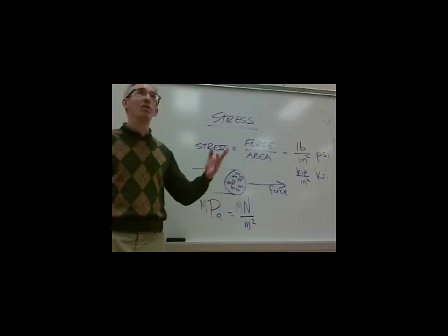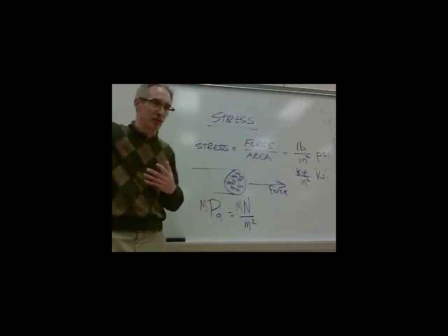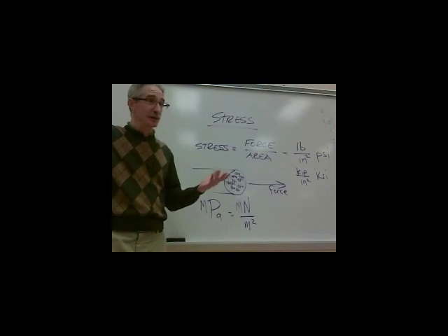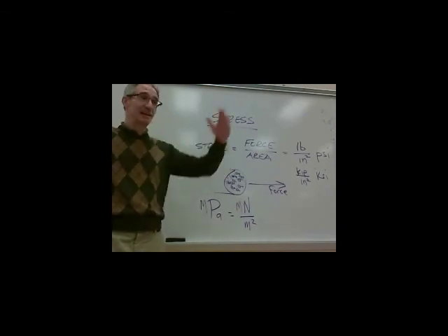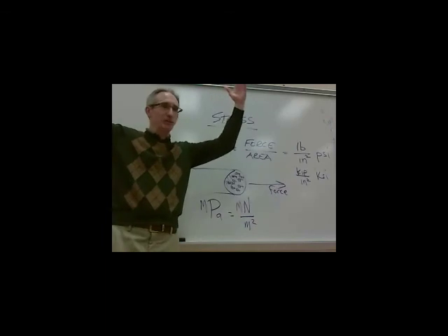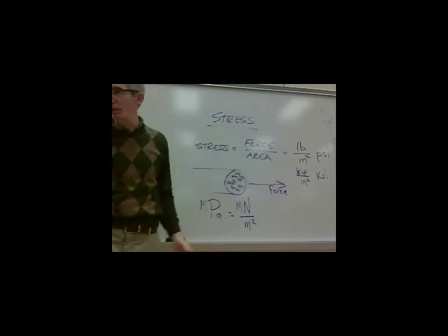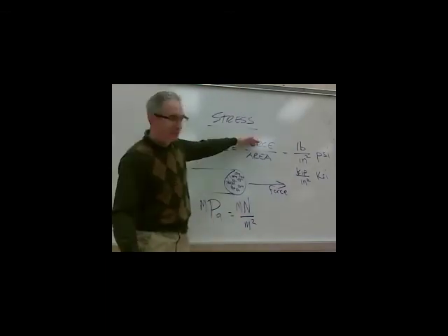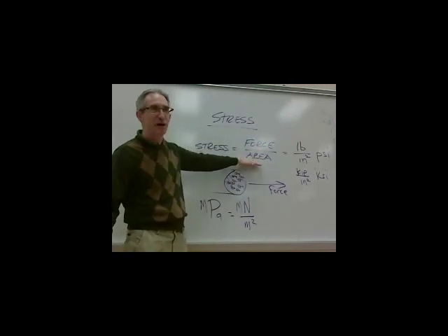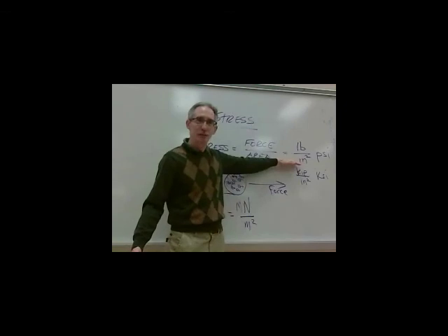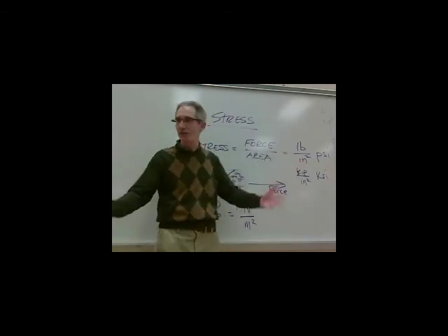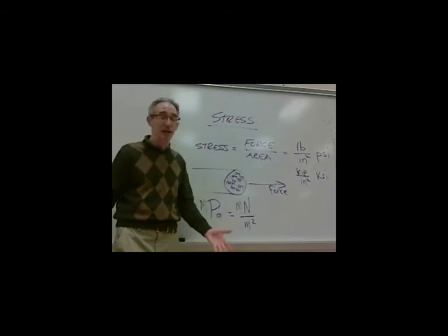I don't know what material it's made out of. 500,000 pounds sounds like a whole lot, but if I've got 500,000 square inches of cable resisting it, 500,000 pounds divided by 500,000 square inches only gives me 1 psi. That doesn't sound like a very big amount of stress. So the correct answer actually is it depends.